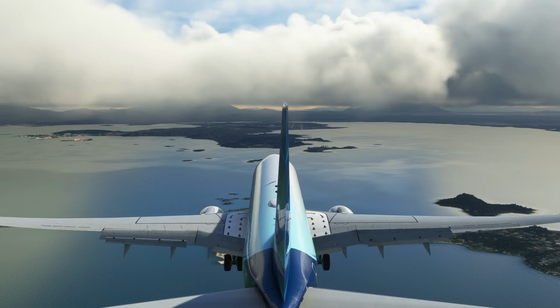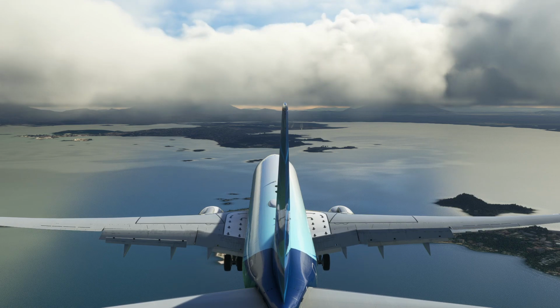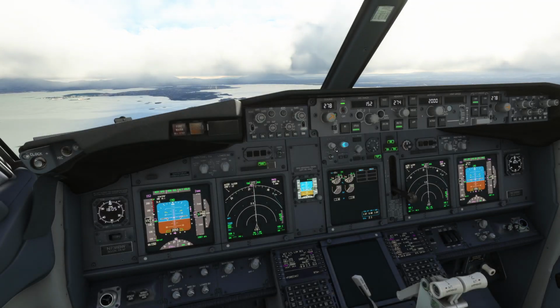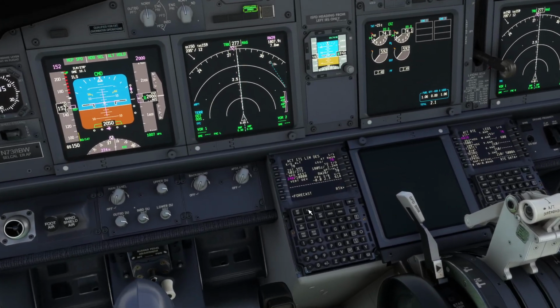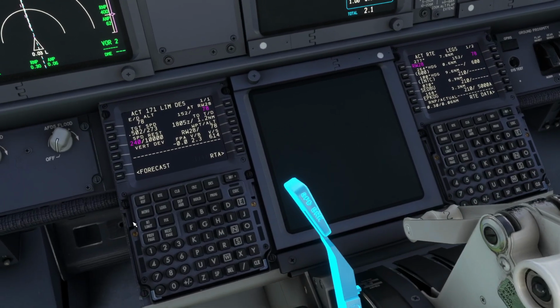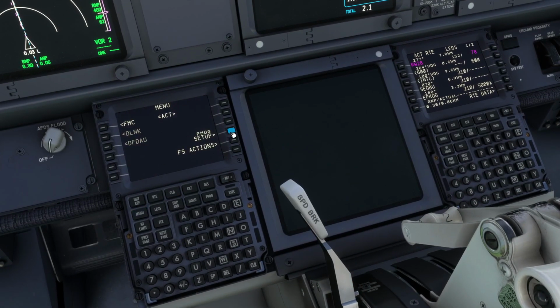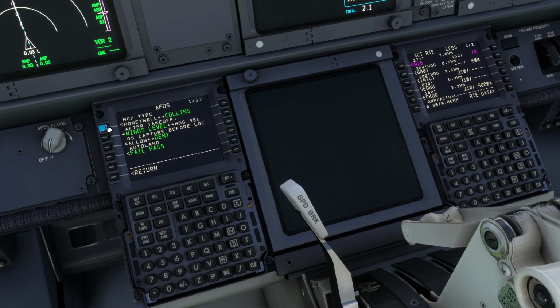So we go to our simulator again. As you can see, we are on a final approach here. This is runway 28 in Rio Galeão airport. So when we go inside the airplane, first thing, when you go to the CDU menu, then you go to PMDG setup, aircraft equipment, and then you scroll down to page 12. On that page, called instruments, you have three options for your head-up guidance system.